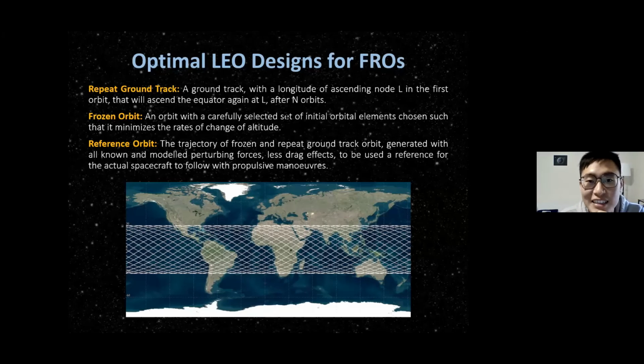How likely are small satellites to experience perturbation effects when in orbit? Most small satellites are in low Earth orbit, because for a geostationary orbit, satellites typically need a much bigger fuel tank to get there, or at least to stay in their parking spot in geo. For small satellites, the biggest perturbing effect is probably drag, especially if you have a large area object, for example, a large antenna or large solar panels.